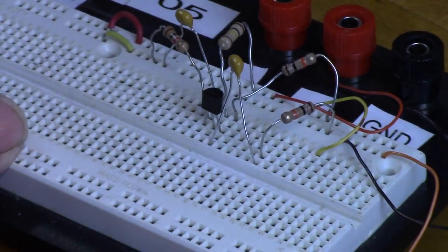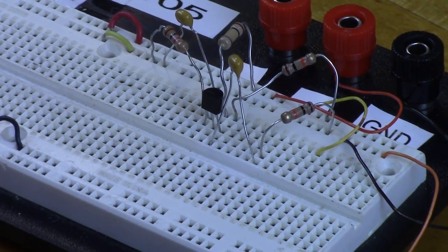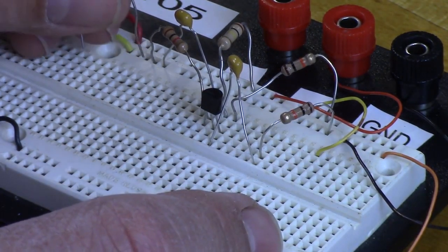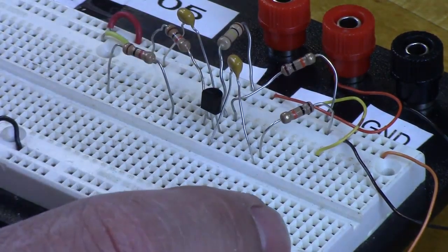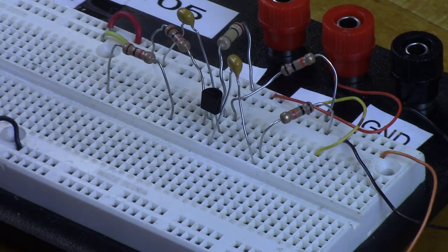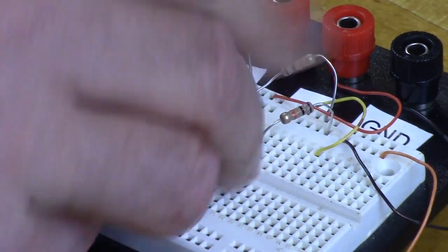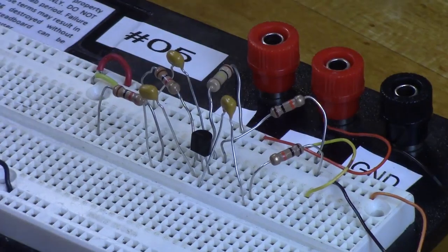And then all that's left is our C1 and R1 and the potentiometer. So here is our RS that goes from the signal generator. We're going to just put that off to the side. And here is our C1 that goes from RS to the base, like so. And now we can connect up our signal generator.